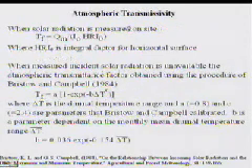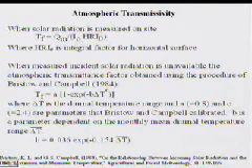The atmospheric transmissivity, when there's measured solar radiation, is just calculated based on the measured solar radiation relative to what the solar radiation should be calculated from the sun angle on a horizontal surface, and then that atmospheric transmissivity is used to distribute that measurement out to other locations if you're applying the model in a grid distributed mode, and to account for the slope and aspect and the different illumination on different slopes and aspects.